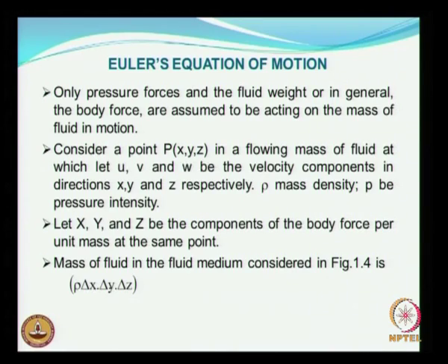In the earlier class we had seen the different kinds of forces, and the corresponding equations also we have seen. Finally it boiled down to Euler's equation of motion, and in this case we consider only the pressure forces and the fluid weight, or in general the body force. They are assumed to be acting on the mass of the fluid in motion.